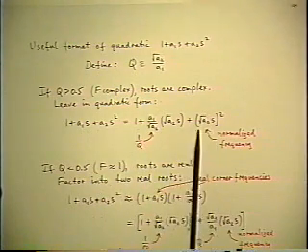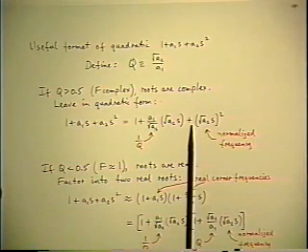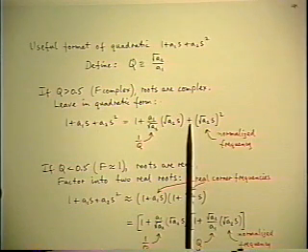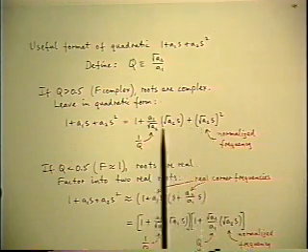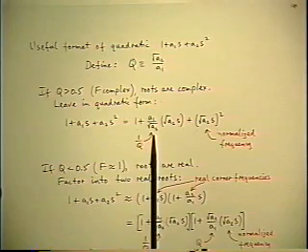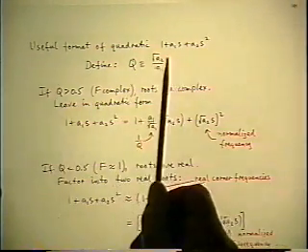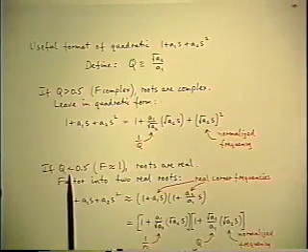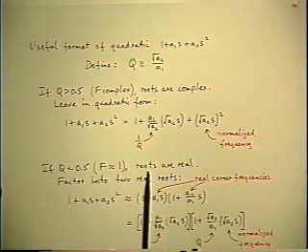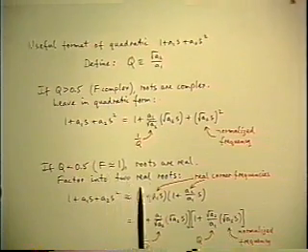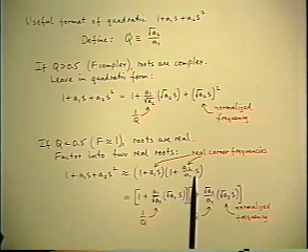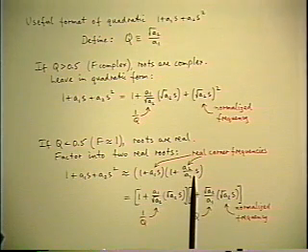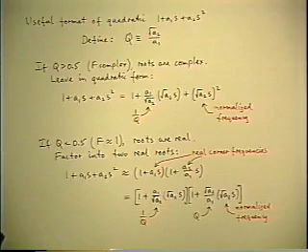which we haven't talked about yet, but we're going to shortly, to do with RLC filters. What you do is you define a normalizing frequency, and there's one parameter left, which is the Q factor. On the other hand, if when you determine the Q from the original coefficients, it's less than 0.5, a good approximation is to take f equal to 1, in which case you factor the quadratic into two approximate real roots, which are very simple.